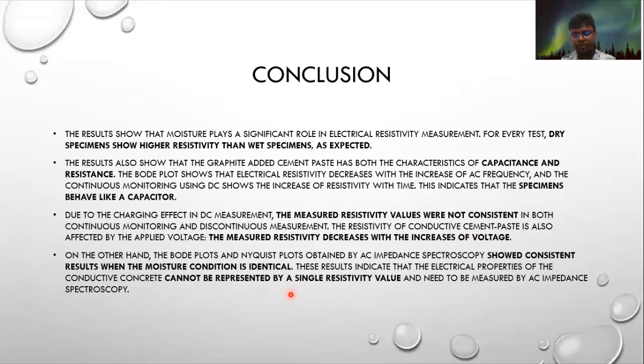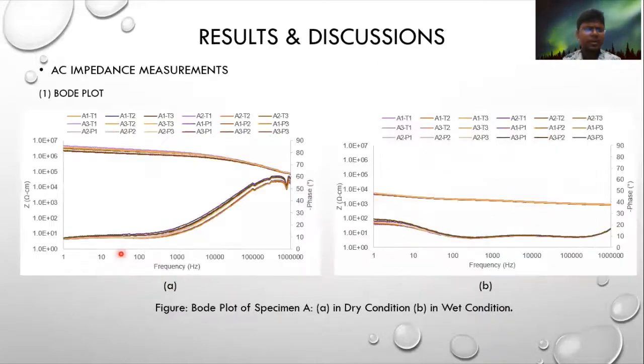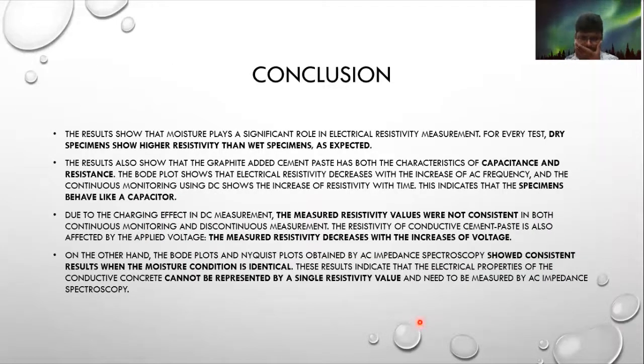Moreover, we can see that our resistivity is varying with the frequency, so we can't have a single resistivity value for our specimen. And we need to measure electrical properties by AC impedance spectroscopy.